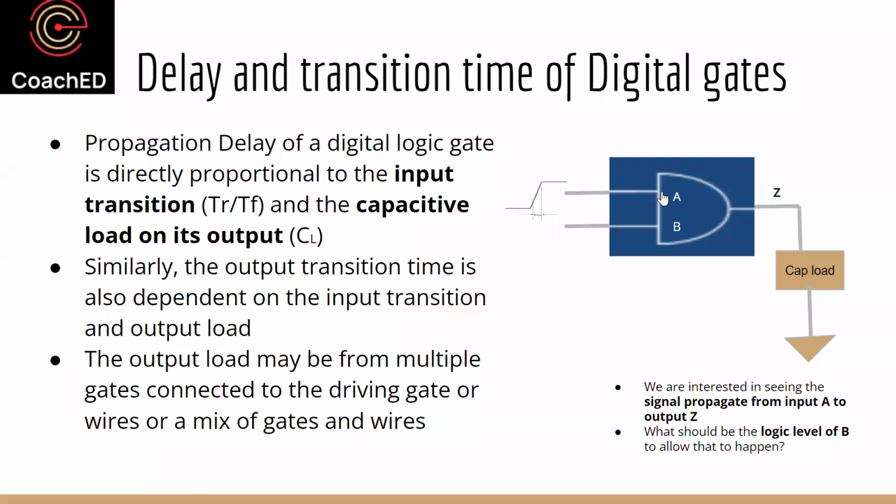And the quicker the transition is, the quicker it switches from its initial state to the later state, and if it is on, its resistance is going to be very small. So both these effects have a direct relationship. I worsen the transition, that means increase this time, resistance goes up, which means delay increases. Or if I increase the load, capacitance goes up, which means delay increases, right?